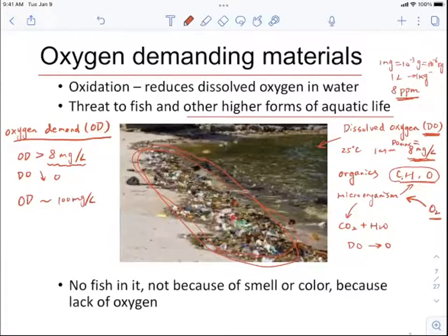So some of them, let's say, the meat plant, right? When people produce meat, we know that there can be a lot of waste and wastewater generated. The oxygen demand can even be higher than thousands of milligrams per liter. Under this situation, we can't directly dump the wastewater into our natural system because it's going to reduce the dissolved oxygen to 0, right?